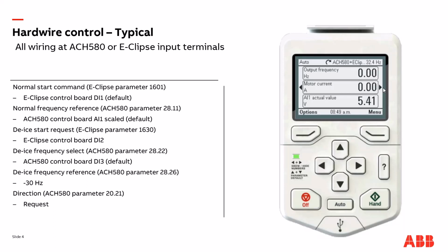And I guess the last point I want to make is that if you're not running currently and you simply activate DI2, you can initiate a start in de-ice mode without having to already be running. And so here from a stop state, I've just activated DI2, and now we are simply starting in de-ice mode. And then I'll open DI2 and the drive will just stop.